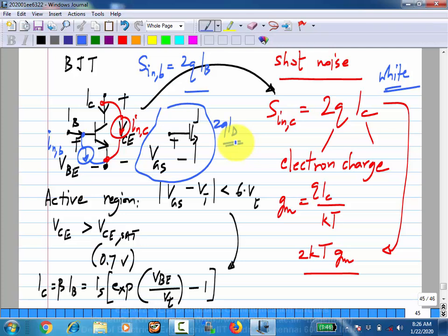If you have a situation where you have large signal excursions in the bias current, GM will also be varying with time. This especially happens with circuits in which you have periodic variations of GM or IC. So then you have essentially cyclostationary behavior where it's hard to define what the noise spectral density is, but the autocorrelation is periodic. You will have to imagine the noise spectral density at each instant of time and then average it over a cycle. Typically it is difficult to do by hand, but the simulators take care of it. What I am saying is that the signal GM itself will be varying, so the noise calculation has to take that into account. If it is small signal variation, it may not be much, but if it is large excursions, then it may be significant. But the simulators do take care of all those things.